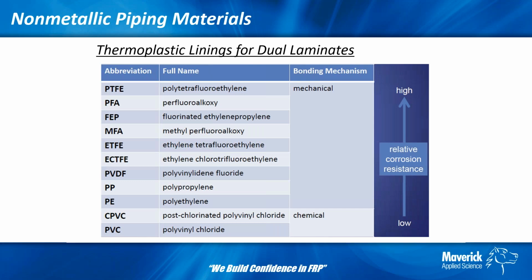If we look at PVC or CPVC, possibly polypropylene, basically the pipe is made from the inside out. You have a steel mandrel and you lay down your lining material on top of that. It may be a tube or it may be a rolled sheet, and then we bond the FRP to it. With CPVC, we have a bonding resin that softens the outside of the CPVC and creates a bondable surface, and then we can wind the FRP directly on that. That bonding resin ties it all together.